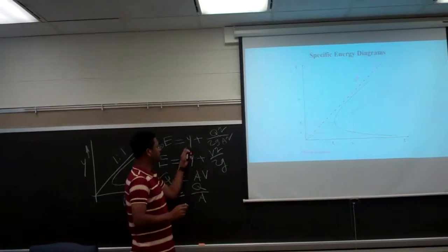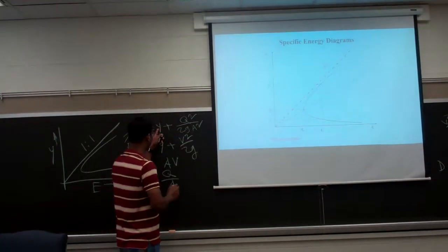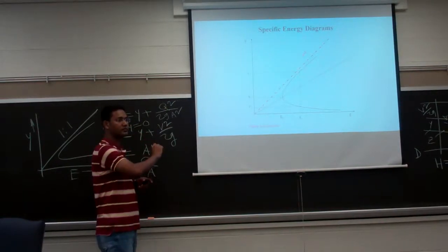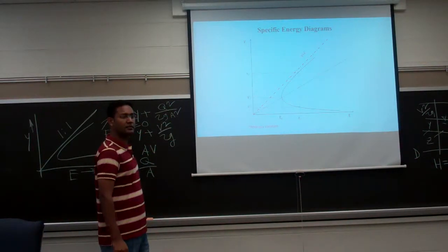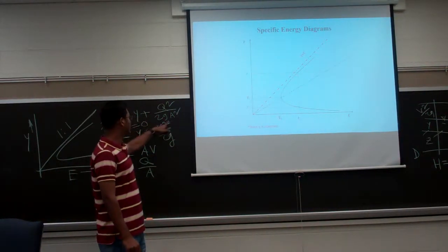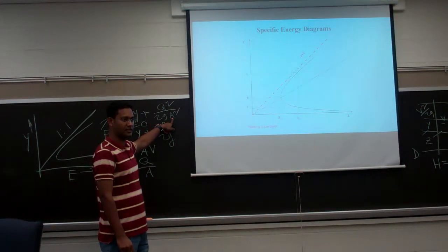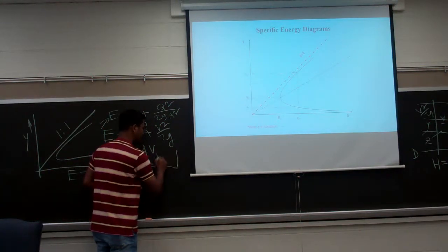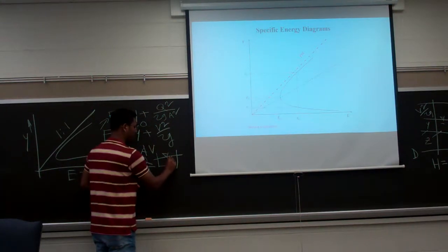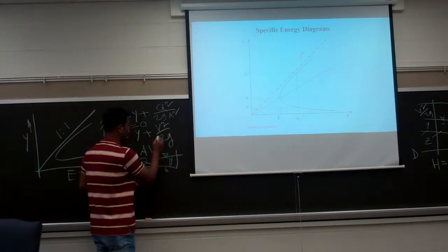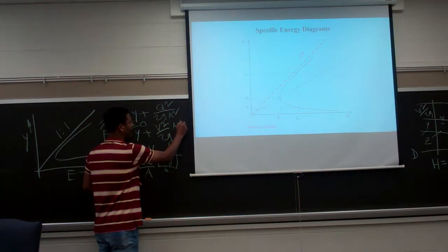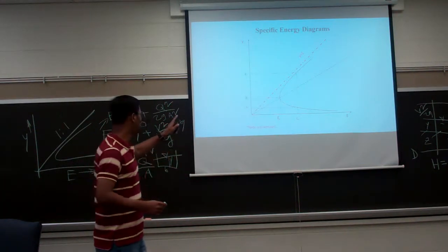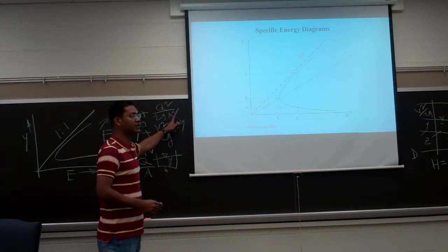So from this equation, if I use y equal to 0, what will be the value of specific energy? Because we have A as denominator, right? So if the cross section is a rectangular section, this is B, so A will be B times y. That means inside A we have depth of water. So if y is 0, the total denominator will be 0.